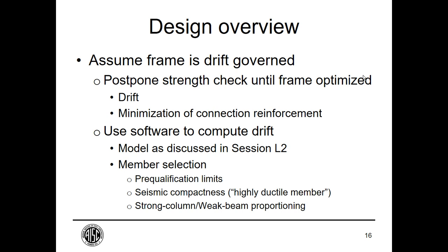And so as we select combinations of beams and columns in our analysis software to control drift, we want to make sure that we aren't selecting too weak a column or too strong a beam. We want to make sure that the pairings work well together.